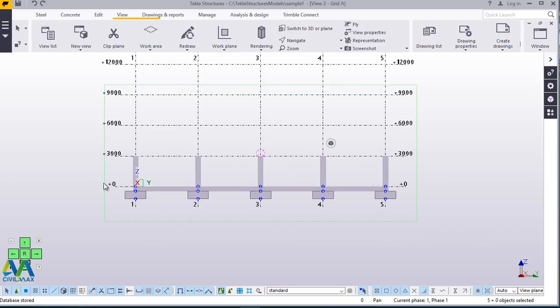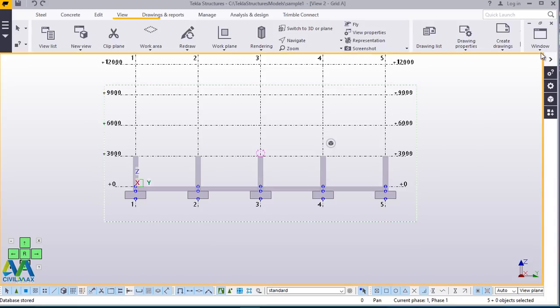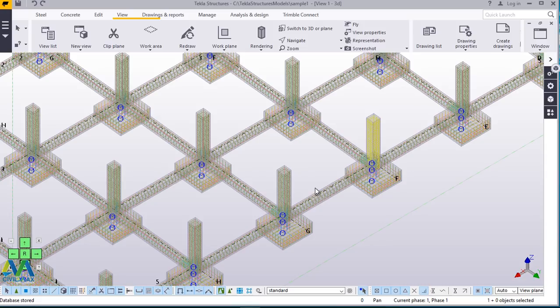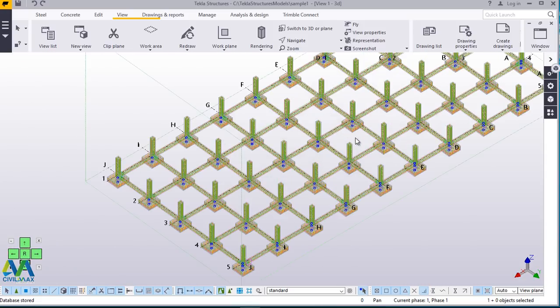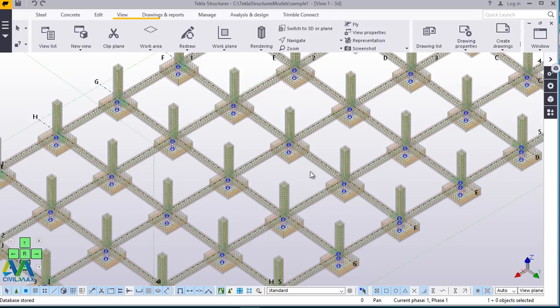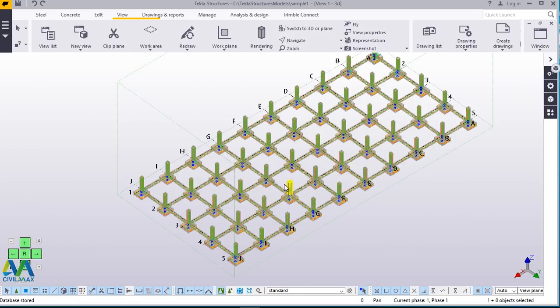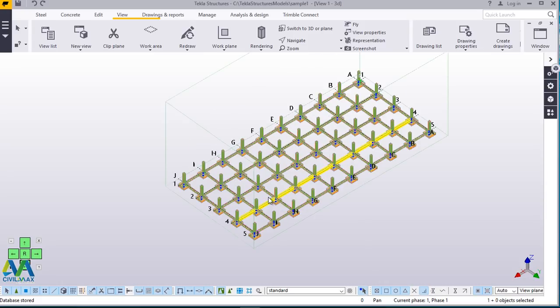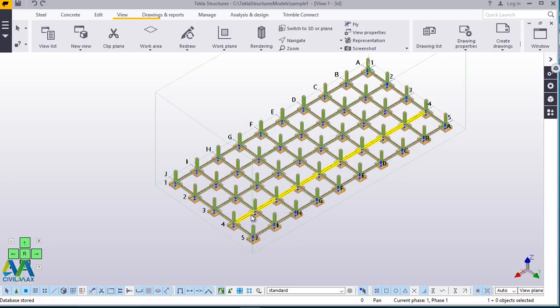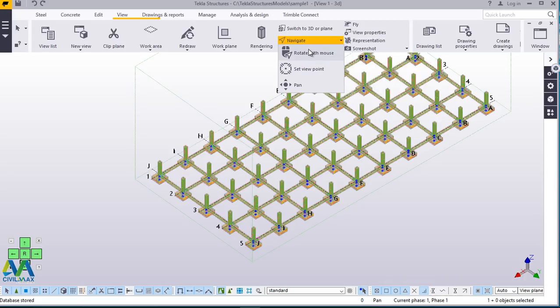And remember, you can change all these heights uniformly to a height of your choice. And the heights of the column rebars will change automatically in accordance with the height of the column.